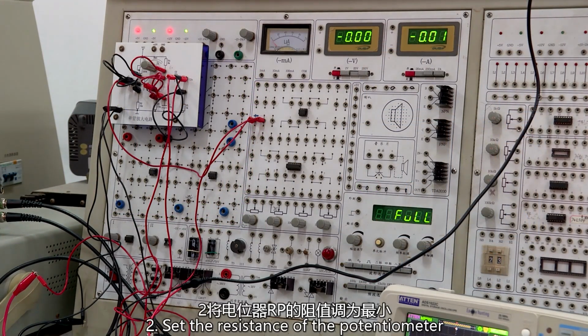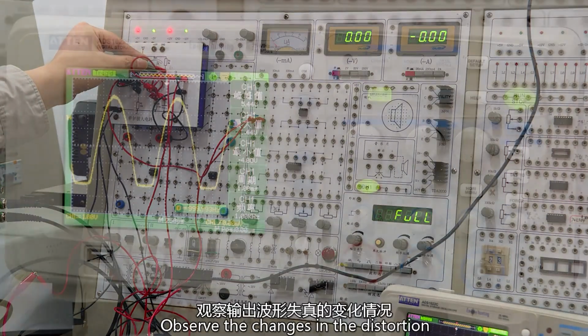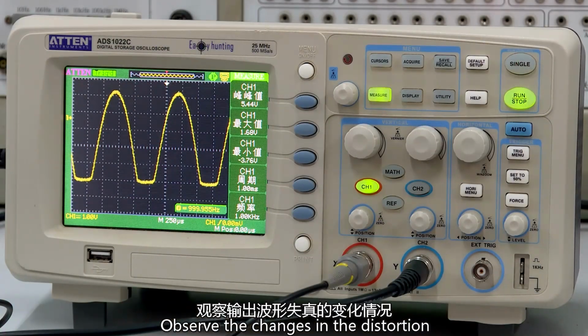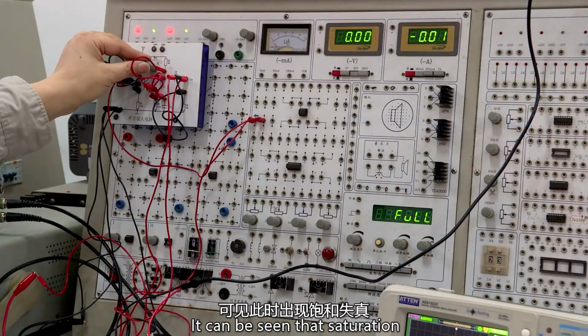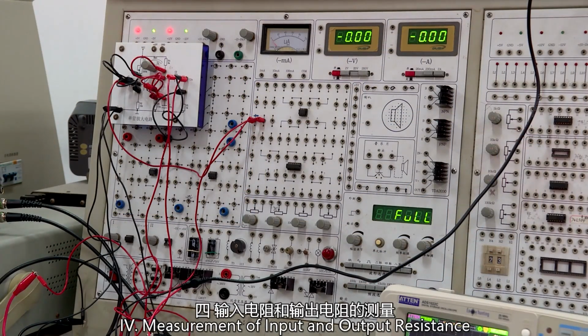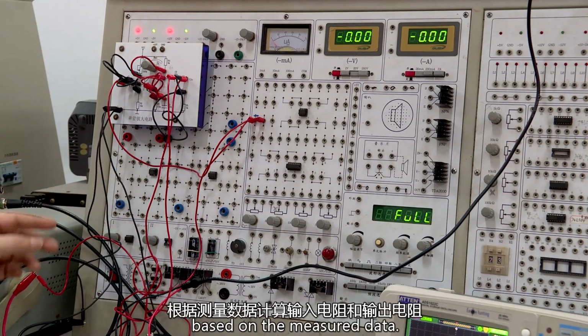Set the resistance of the potentiometer RP to the minimum. At this time the static current increases. Observe the changes in the distortion of the output waveform. Draw the waveform at this time. It can be seen that saturation distortion occurs at this time. 4. Measurement of input and output resistance. Calculate the input and output resistance based on the measured data.